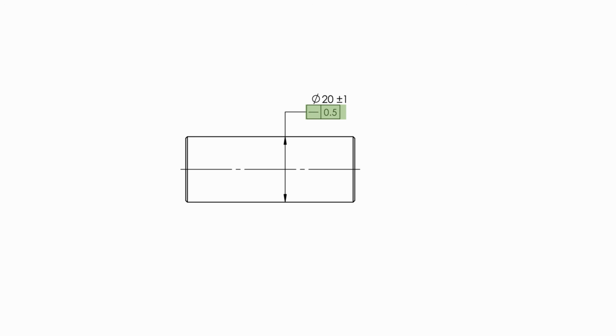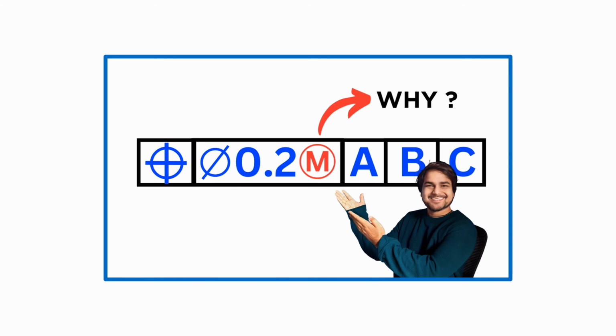Whereas a geometric tolerance without any modifier is difficult to inspect. You will need a CMM. But we cannot always define an MMC modifier with every geometric tolerance. It all depends on the application. More about that in this video.